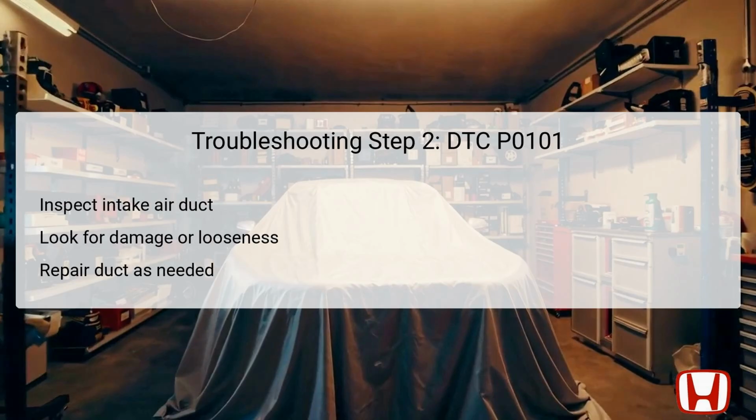In the second troubleshooting step, focus on the intake air duct, specifically at its connection to the air cleaner. This visual inspection is critical, as any damage or looseness can result in unmetered air entering the engine. Such discrepancies can skew the readings provided by the MAF sensor, leading to performance issues. If the inspection shows that the intake air duct is intact and secure, you can move on to the next step in the troubleshooting process.